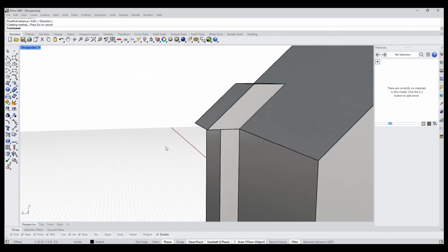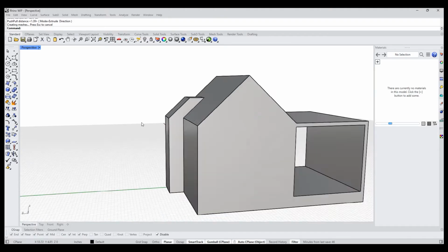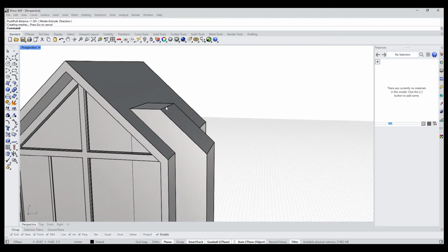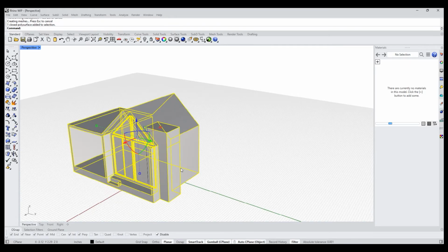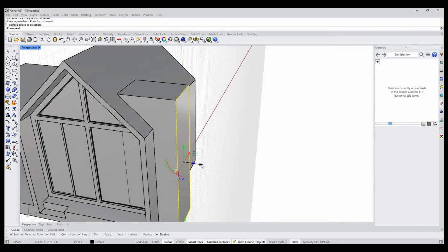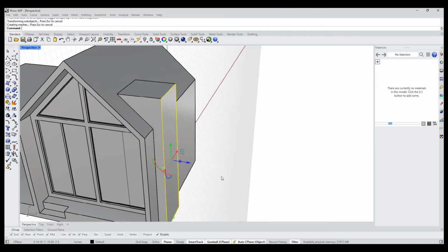Like that, and then I'm going to push-pull this to snap to that, and then I don't want this face to translate over like that, so I'm going to move it, and I'm going to snap it vertically, and then I can merge all faces. So now I've got that little detail pulled out. I can adjust that with Gumball. I can either pull it in or out.